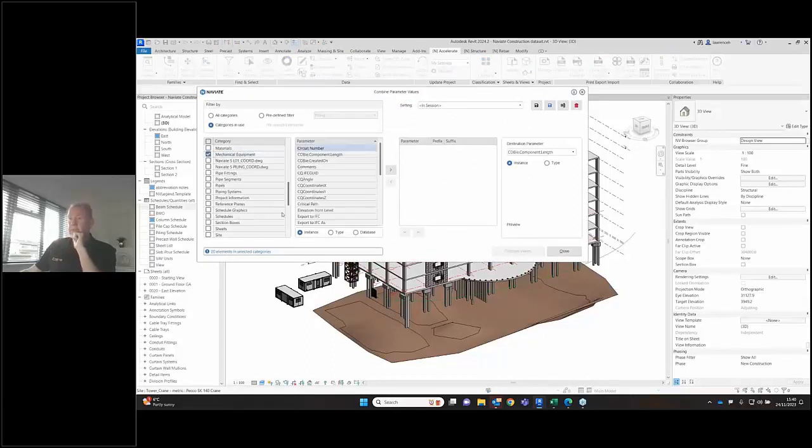So that's this one in here. Of course, we're looking at type information now. So we'll go down and find those pieces of data that we were just talking about earlier on. I want the width, the depth, and the height. Now, I want to join these together with an X in between them all. Like so. Actually, I don't need the space afterwards. I need the space preceding the X.